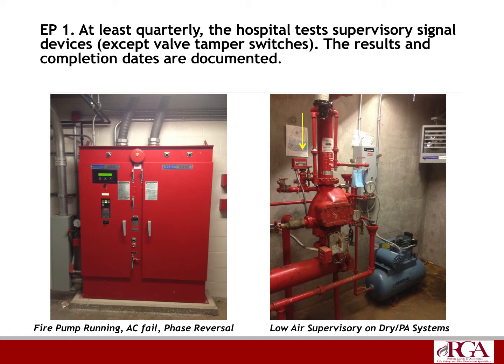A supervisory device is a device that monitors components and doesn't necessitate the fire department to come out, but rather it needs immediate action. So it's supervised. And then you have your trouble signal. Your trouble signal just tells you that there's a malfunction on the fire alarm system. So these supervisory devices have to be checked quarterly. They have to be inspected and tested.